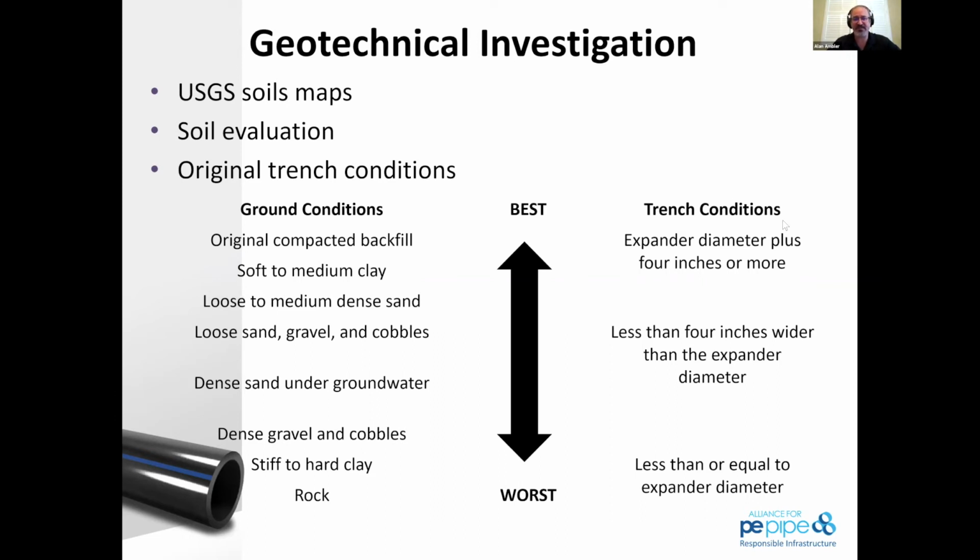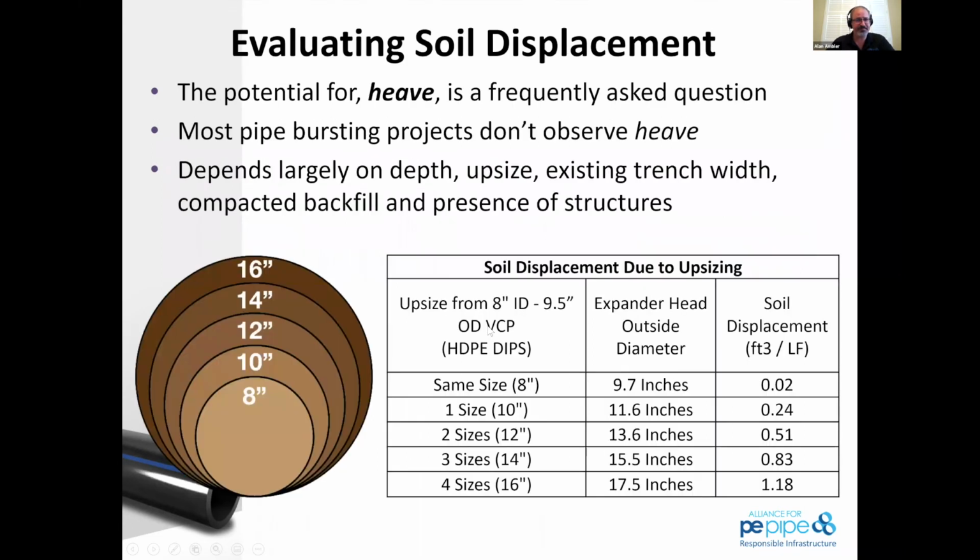And then we look at that expander plus 4 inches or more. So we're looking at the expander head, not the existing pipeline, as we continue to go through that. So we talk about soil displacement. This varies fairly significantly across the country with soil conditions. And it also varies based on depth and contractors' experience.